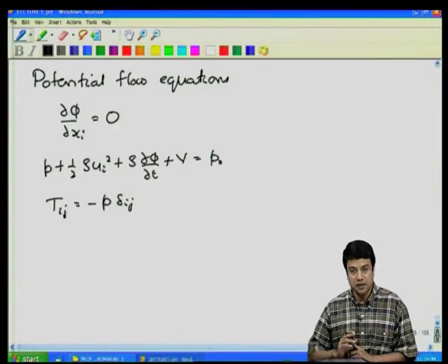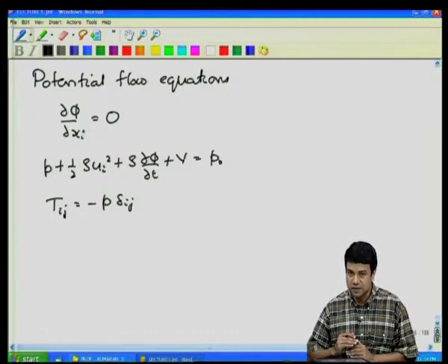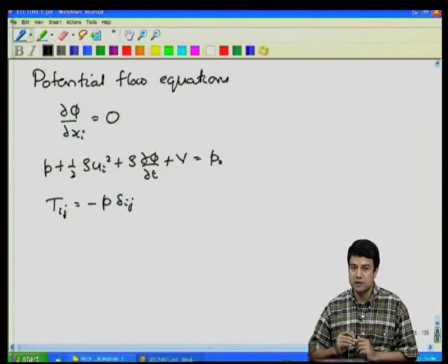We neglected the viscous stresses. Because we neglected the viscous shear stress, there is no momentum diffusion from the surface. When there is no momentum diffusion from the surface, one cannot apply a 0 tangential velocity boundary condition at the surface, or a 0 shear stress condition, or a constant shear stress condition, because there is no mechanism for transporting momentum along the flow direction.